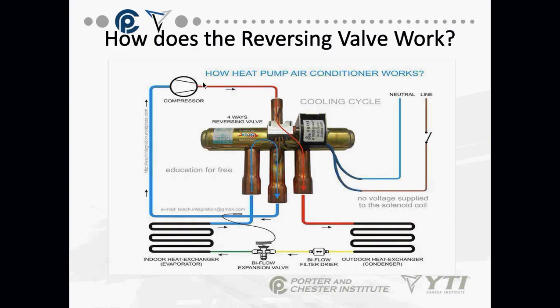The discharge on my compressor always comes into the center port at the top of my reversing valve. Doesn't ever go anywhere else. Always comes into the center port. My suction side of the compressor always pipes into the center port on the bottom of the reversing valve. So my compressor always connects to 2 points on my reversing valve. Always.